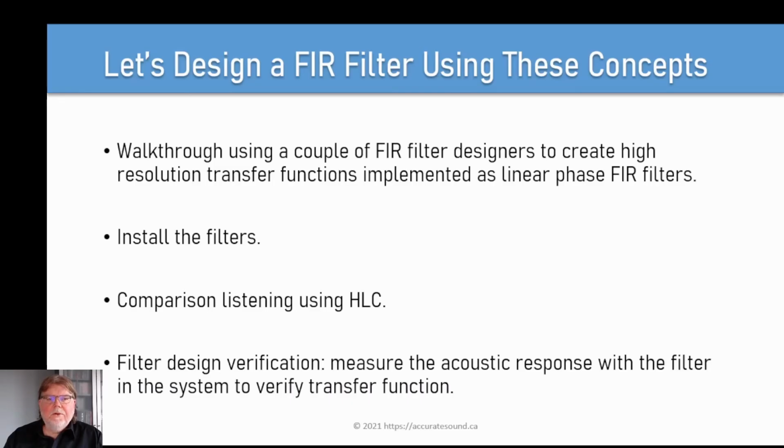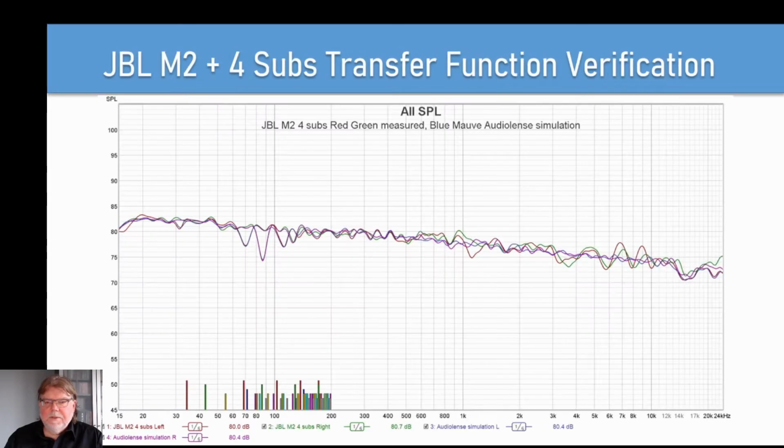All right, we're on the home stretch. Next up are a few examples of validating the FIR filter designer simulations with acoustic measurements. Remember the JBL M2 with 4 subs? I've exported the audio lens simulation into REW and taken measurements of both the left and right speakers with subs.